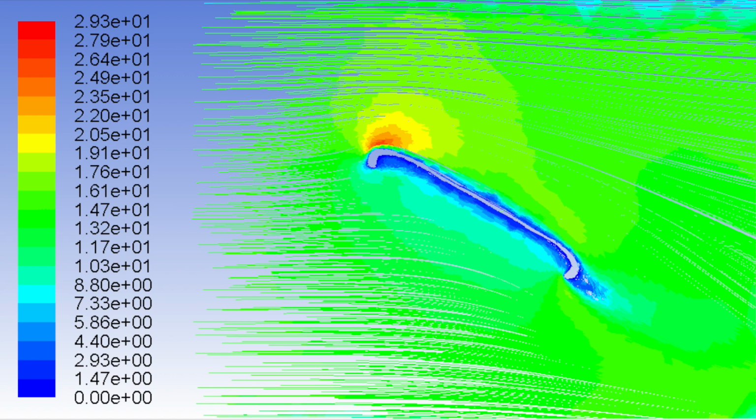Looking at the ANSYS simulation, the drag at the tail has increased even further and the lift being generated is increasing. However, the ANSYS model does not take into account the slowing of the frisbee as it travels through the air. So in reality, at this point, the frisbee would have reached a condition where the force of drag and gravity overcome the lift and initial propulsion, causing this frisbee to stall.